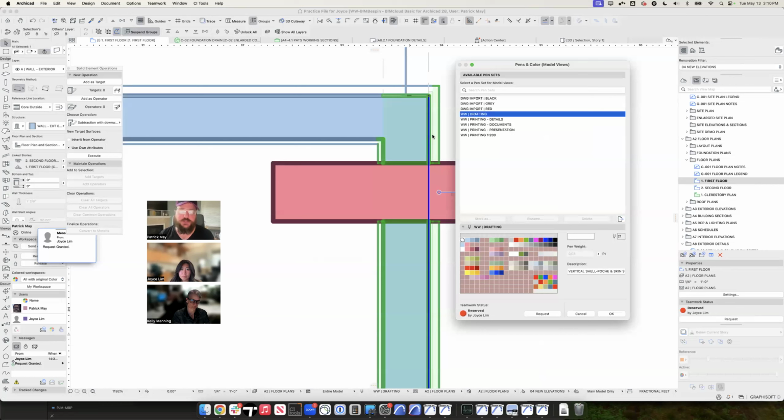Because on our quarter-inch plans, we don't want to show 5/8 inch plywood, 1 inch air gap, 3 inches of furring, siding, whatever. We just want to show here's the framing, here's everything that's outside of the framing. Simplify it down for the quarter-inch scale.